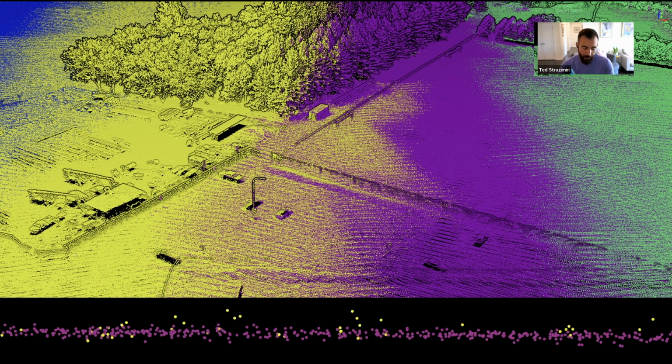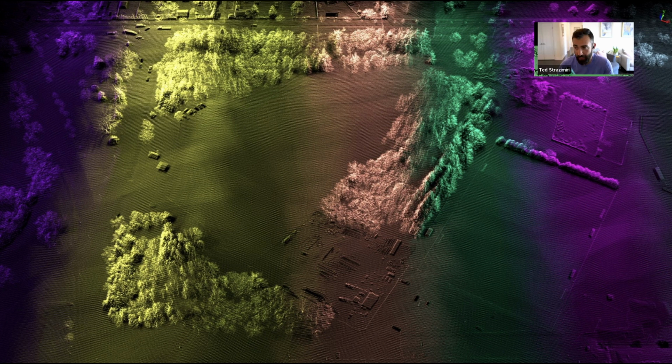Overall, it's on a case by case basis, though, right? If you want the utmost accuracy and precision from your data and you need it for what you're doing, do that strip correction and do that strip alignment, do the cutting. I think the cutting is also one of those things you can probably skip if it's a forestry data set, right? Or if it's more of an engineering use case, more of a survey use case, you definitely should be cutting and aligning. But again, everyone has their own workflow, and I think every tool is also slightly different in how straightforward or how easy it is to get to that strip alignment and how much effort it requires.